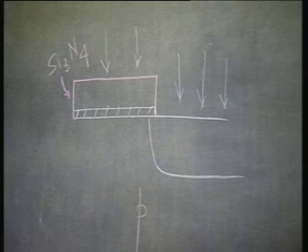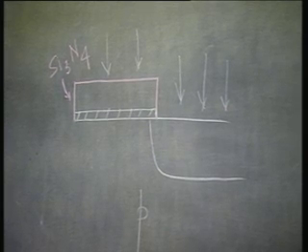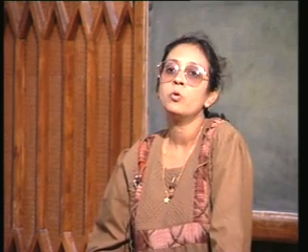Okay. Now, in the next step, you carry out the drive in, in an oxidizing ambient. You see, you want to have a deep NP junction, right. So, you carry out the drive in an oxidizing ambient. So, what will happen? Oxide will form over the regions which are not protected by the nitride and oxide mask.